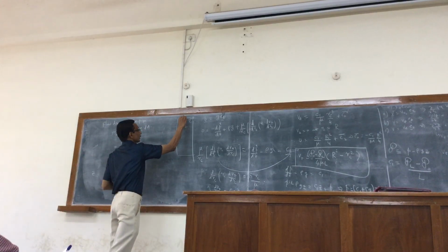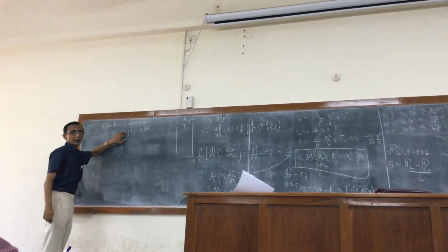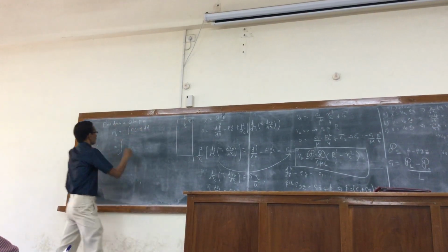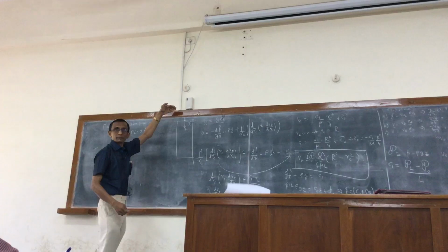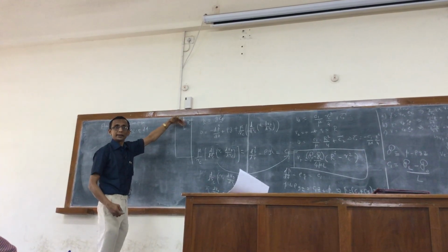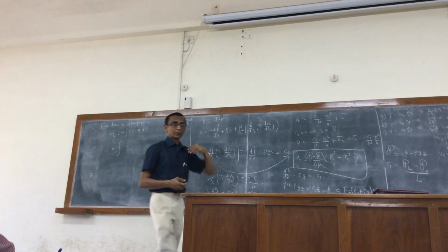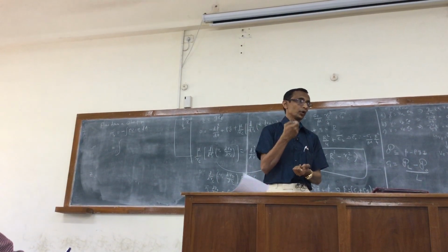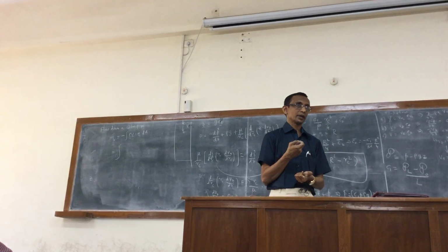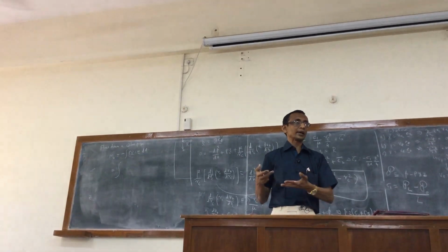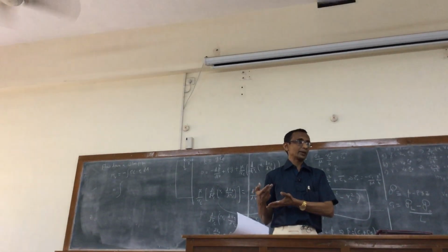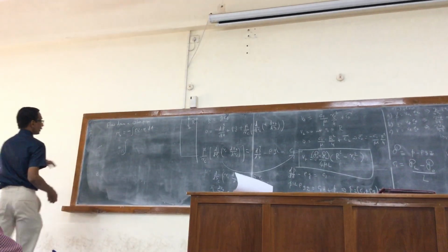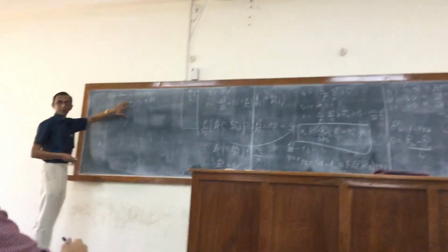If I'm looking at it as inlet, this will give me the mass efflux. So at the top, for the mass influx, if you focus on the entry, I have to make it minus rho v dot n, where n is the outward normal vector. If you don't take care of this, you will get a negative answer, which of course doesn't make any sense. The flow rate is a scalar, so we can adjust the negative sign suitably.